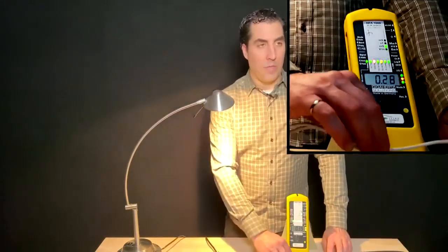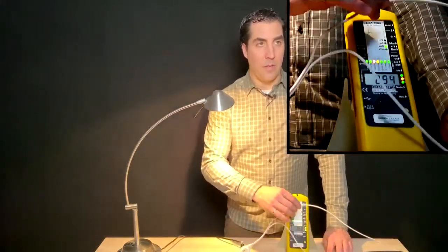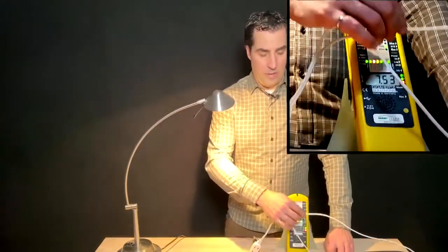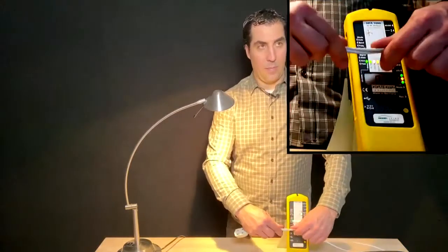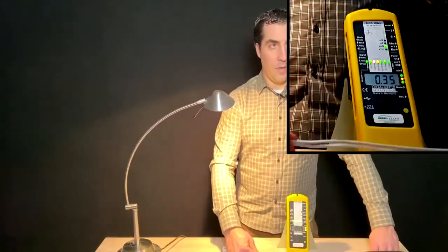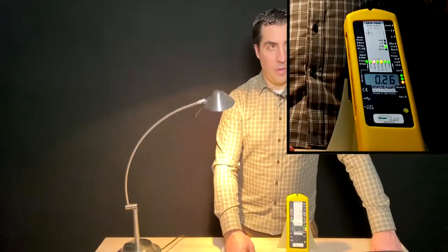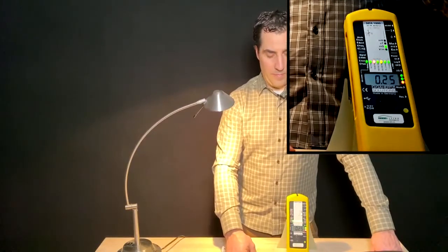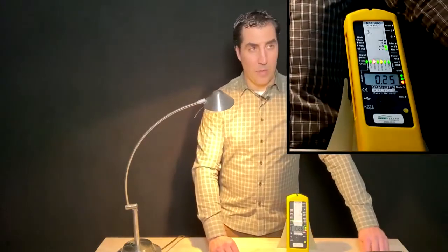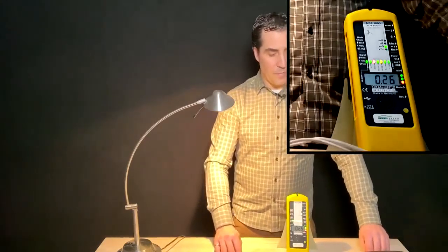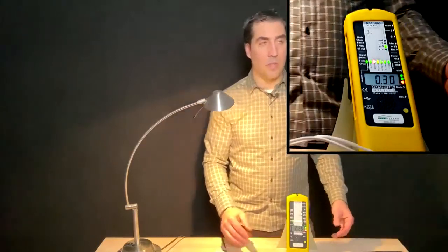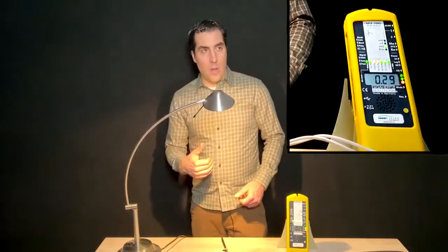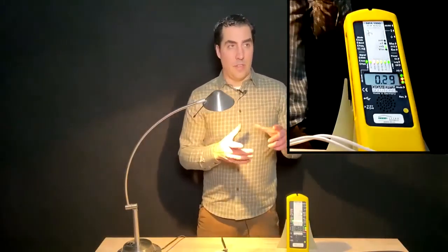Now, as we separate these wires, the magnetic field increases. And if we zip them together, right, it drops down to almost the background level. So what happens when we're exposed to magnetic fields? Well, magnetic fields will induce a current in anything that's conductive, or anything that's a closed loop, I should say, that's conductive.